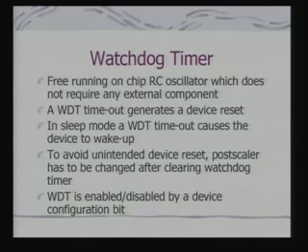So a free-running on-chip RC oscillator provides the input for this timer, and it does not really require an external component as a clock source. A timeout generates a device reset, so the device is reset to the initial state. In sleep mode, a WDT timeout causes the device to wake up. That is, when the device is sleeping, if this timeout occurs, the device will wake up and start processing.